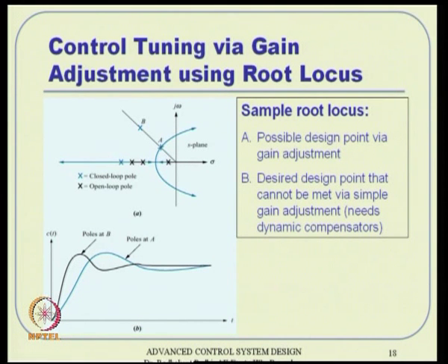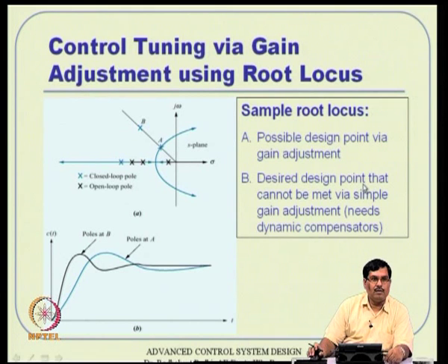Now after we plot the root locus, we should take advantage of that to the best extent possible actually. It helps us in tuning the gains in a good way. Now there are some ideas in classical control that if there is a higher order system, you can roughly interpret that as a dominant second order system, and you can keep only the dominant poles. Then you know the settling time formulas and all that, assuming that there are no zeros in the loop and only 2 dominant poles. For that particular approximation, you know the settling time characteristics and percentage overshoot, things like that actually.